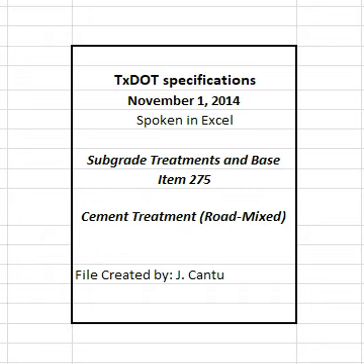Reimburse the department for subsequent mix designs or partial designs necessitated by changes in the material or requests by the contractor. Limit the amount of recycled asphalt pavement to no more than 50% of the mix unless otherwise shown on the plans or directed. 3. Equipment. Provide machinery, tools, and equipment necessary for proper execution of the work. Provide rollers in accordance with Item 210, rolling. Provide proof rollers in accordance with Item 216, proof rolling, when required.